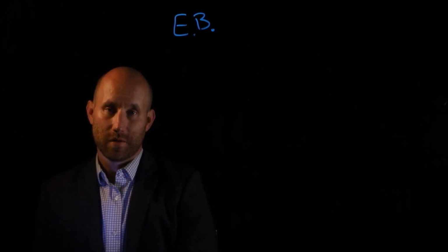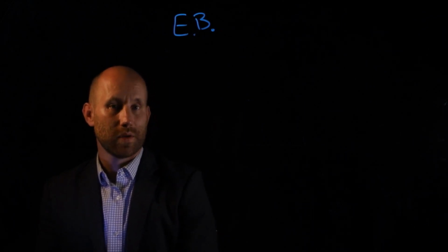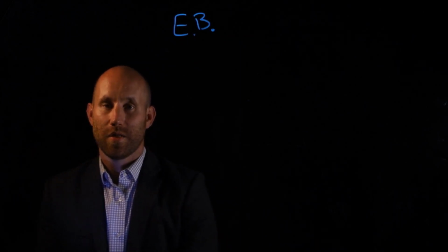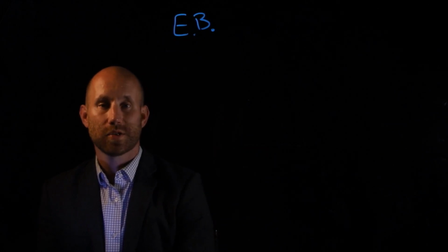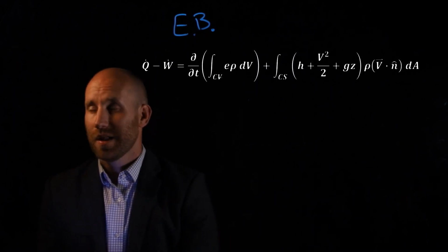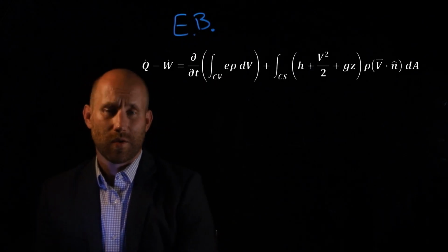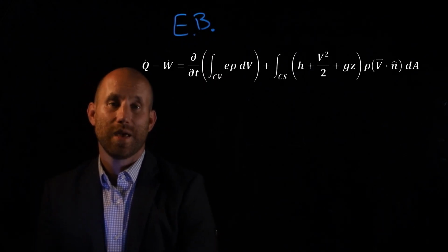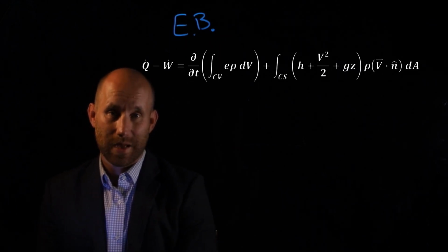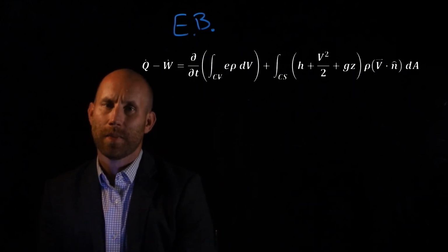Moving on to our integral relationship for our conservation of energy, or our energy balance, it's going to look very similar. The terms are very similar. Now we just have integral relations for integrating the entire control volume as well as our control surface to account for those fluxes of energy crossing. So adding the equation here, left-hand side of this equation, we've just moved things around just a little bit here. Left-hand side, again, is our rate basis of heat transfer and work transfer as it crosses our system boundaries. Our sign convention is the exact same. We just now have to account for that just like we previously did within the lumped capacity.